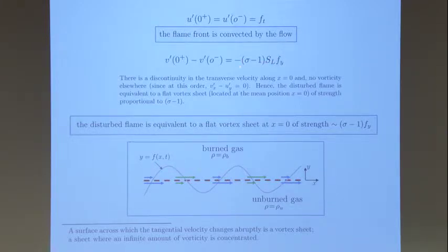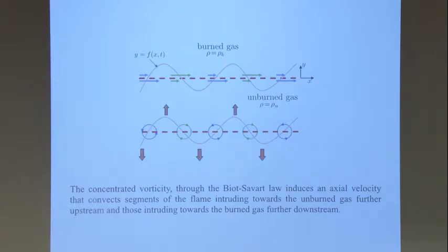Slope of f is positive, meaning that the burn velocity is smaller, right, because of the negative sign, means it's smaller than the unburned. So the blue burn is smaller than on the unburned side. When the slope is negative, right, this is going to be positive, and so the velocity above is larger than the velocity below. And it goes the same in the rest of along the flame. So what does that mean? It means that there is a vorticity here which is counterclockwise, and here clockwise.